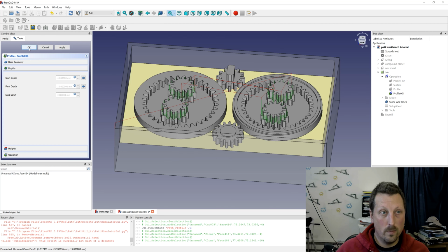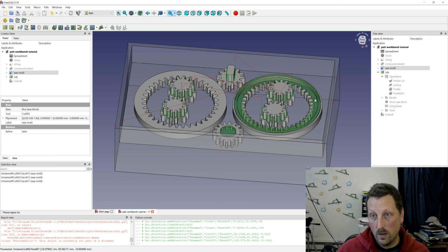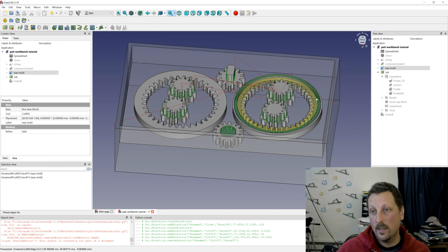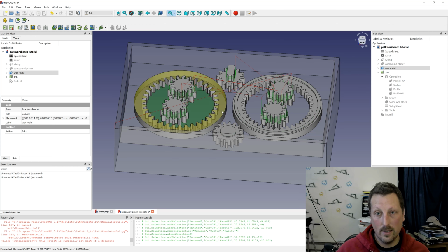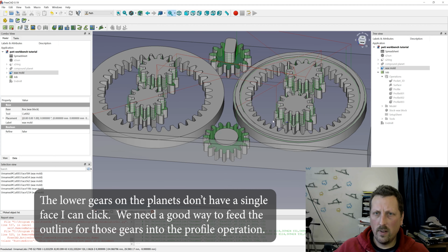So now let's do this one and this one. These are the 1 millimeter tall profiles, and also this one. No, that doesn't work. So you can't select multiple geometries where one is contained completely within the other one. It'll only give you the outside of whatever geometry. So if I selected the inside here and the outside here, no matter what, it will never use the teeth, because the teeth is completely contained by this other geometry. So I'll only ever be able to get a circle out. These profiles aren't continuous, so it's only those little tiny shapes.